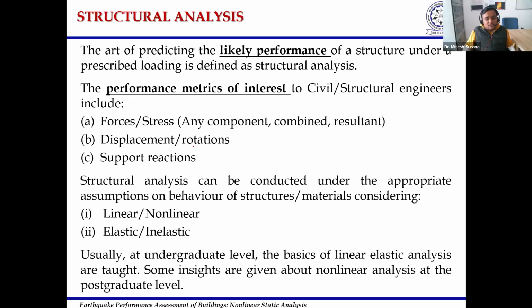And then displacements or rotations are the other response quantities of interest. And sometimes we are also interested in knowing the support reactions. So all these quantities we determine when we perform structural analysis. The simplest example to understand it could be a beam or a column, or analysis of a simple truss and other frames and other structures. So in all types of these analysis, we determine forces, displacements, and support reactions.